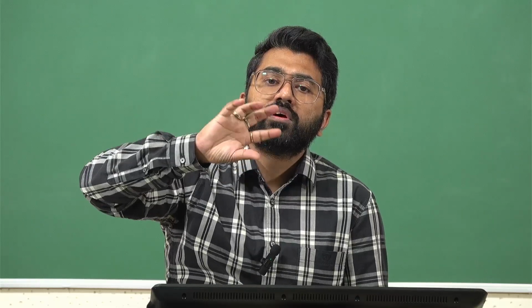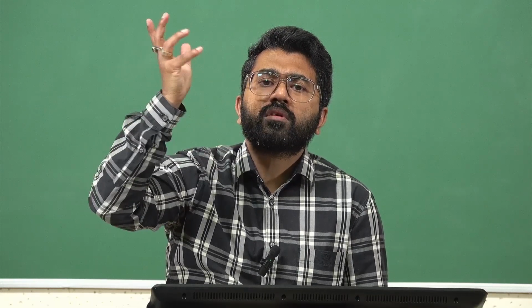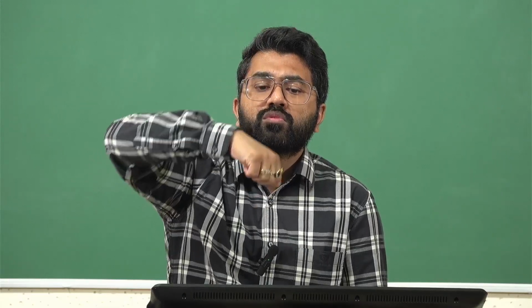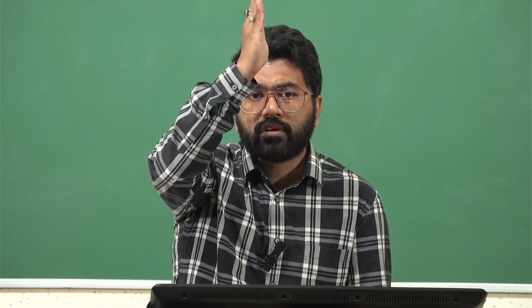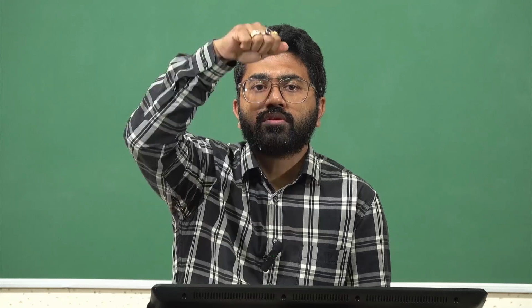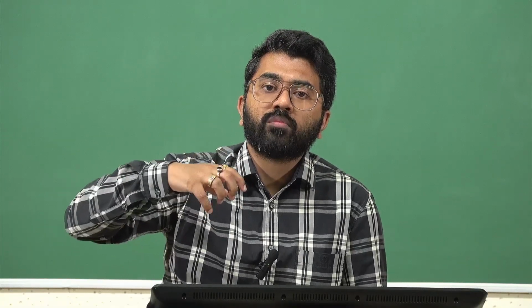Displacement, like I've said, can be measured in terms of how much the tissue has moved. Typically this is back calculated from certain gears, how much they have moved, and we call this the crosshead, and it is going to move along a linear direction, along a line, right? So this is the uniaxial. The test is only performed along an axis, that's why it's known as uniaxial, right? And the load cell, which is typically present as a part of the bottom of the instrument, will take the forces which are generated. So force versus displacement converted to stress versus strain, right?